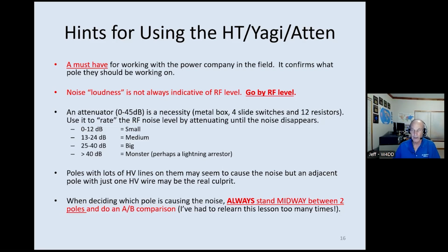And the way I compensate for that, when I'm measuring strength of poles and deciding whether it's on my left-hand side or my right-hand side, I stand midway between the two poles. So you equalize the distance, and distance is really an important factor. And I do an A-B comparison when I'm flipping in the attenuation, and sooner or later, when you flip in enough attenuation, you go, hey, I don't hear it to the left, but I do hear it to the right. I need to go to the right, walk down that way, and do the same thing with the next pole.